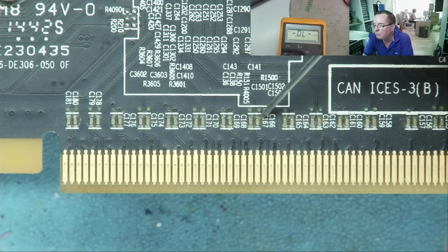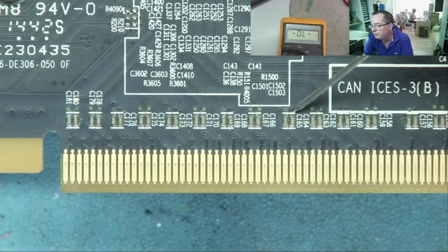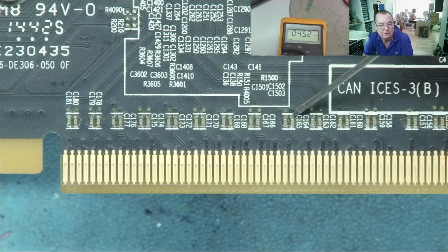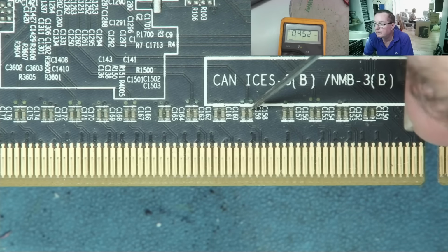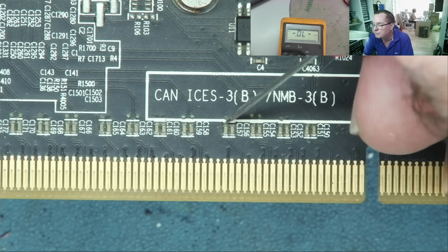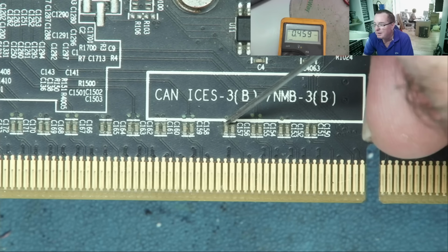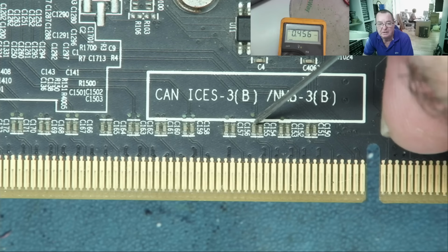I'm just looking at the recording length, so it's taken me 5 minutes so far to go along this board on the PCIe, and that's including the time taken to talk to you guys and describe what I'm doing. Especially with this bit of corrosion, this method will certainly help you find any broken tracks between here and this GPU, or bad connections.